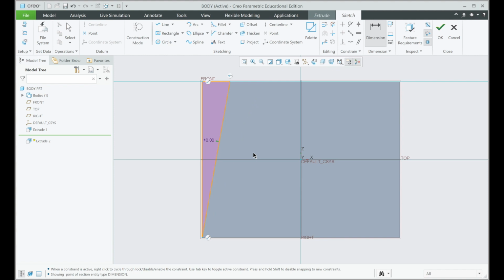Now, normally you do a cut, copy, paste job if you were copying something. We actually have to mirror it. So to mirror it, we use the select tool, and we highlight everything we've drawn. So all that purple area, we're going to click the select tool and draw around. So we'll draw around it like that. When we know it's done, it will have a green outline, and then we're going to mirror it. So this is why it was important we didn't cross that center line.